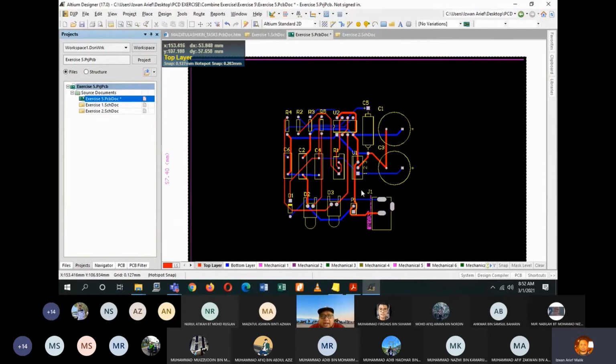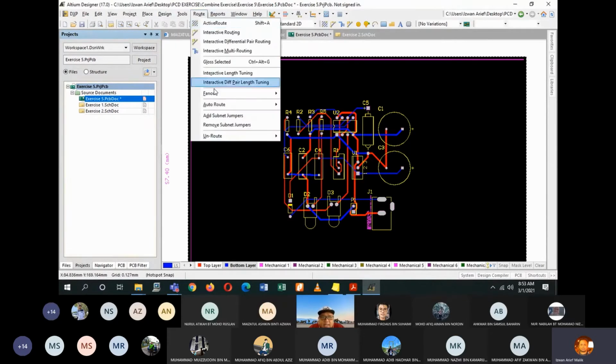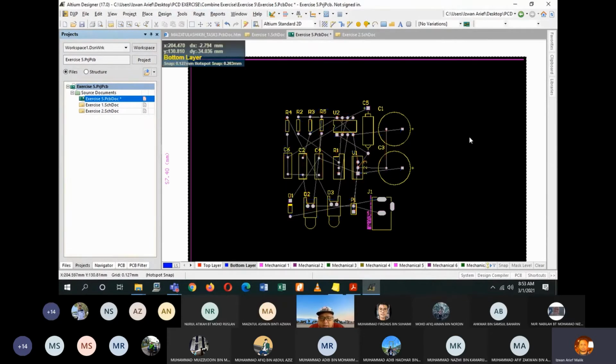So this is my circuit. Alright. So I have blue and red lines. I hope you still remember what blue and red lines stand for. Just look into this part here. Okay, red lines for top layer, blue line is for bottom layer. Let's say you are not satisfied with this circuit here, just unroute them, unroute all, so you get this back. Okay, avoid these things. Okay, like this, avoid being too close.